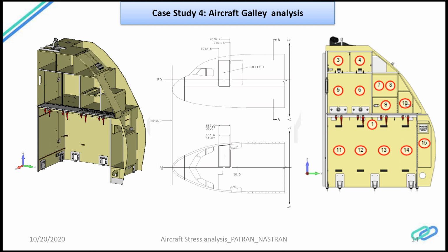If you ask me, I would first come back to the model. I would check why the attachment is having the high loads. Is it due to the assumptions? If all my things are correct, that means the galley is experiencing a very high load, or is my load path correct, or the connection between the panels correct?